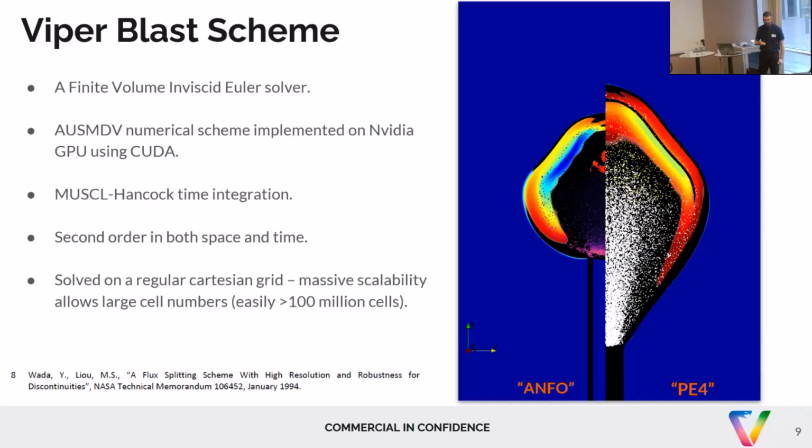We also have built in a selection of explosives you can use. And as you can see here, it's the same simulation, but just two different explosive materials, and the results are already quite varying. So you can either use some of our own built-in explosives, or if you have your own bespoke explosive, you can put in those properties, model that yourself, and those properties remain just within your own input deck, so they remain bespoke and private to your own company if security is an issue with that.